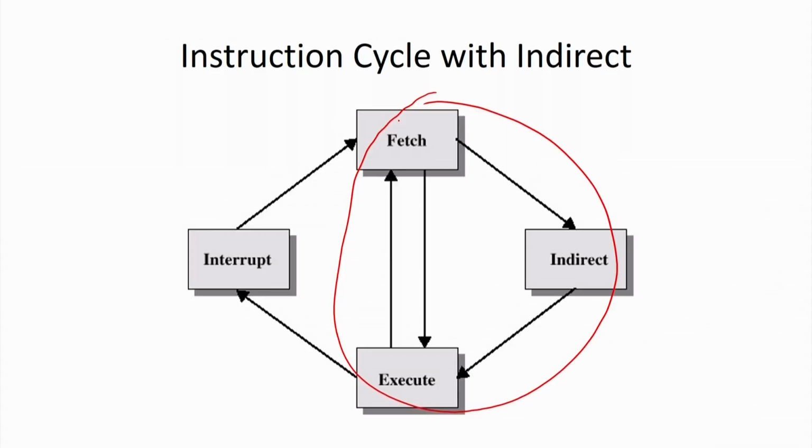So, when executing a program, if an interrupt arrives, so we are getting an interrupt from the interrupting devices or the I/O module, then what will happen? After completion of the instruction, before fetching the next instruction, we will go for the interrupting device, or we are going to execute the interrupt service routine. At that particular point, first of all, we have to retain the processor status. We are going to push all the information to the system stack. Then we are going to execute the interrupt service routine to give the service for that interrupt, and after completion of that interrupt service routine, that means one data transfer is over, we are going to restore back the processor status. That means, we are going to pick up the information from the system stack and put it into the relevant registers.